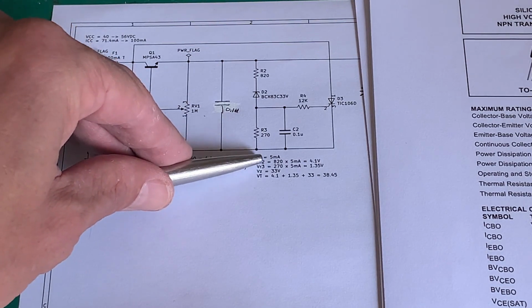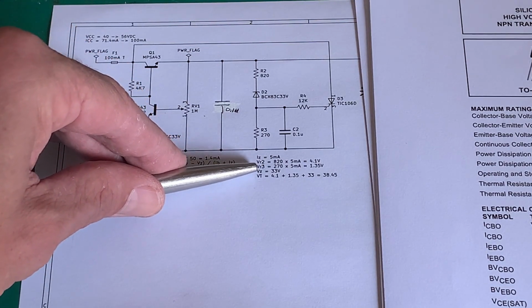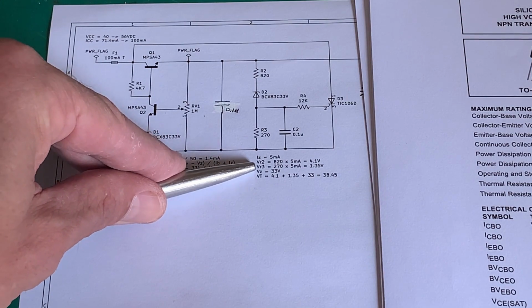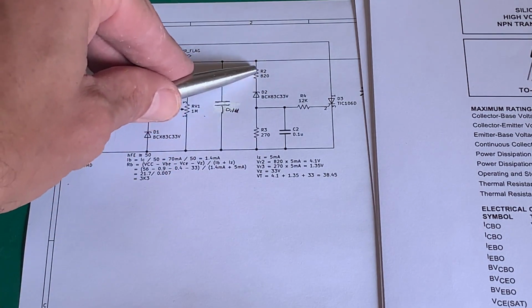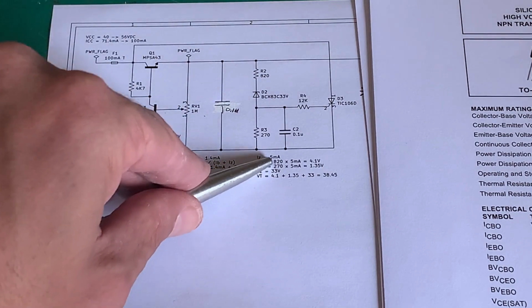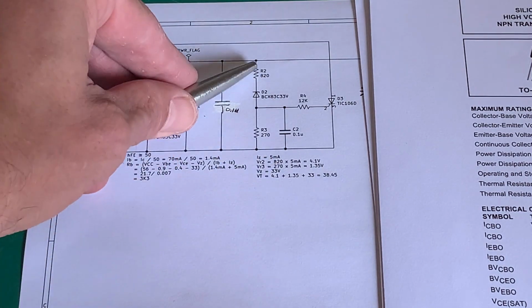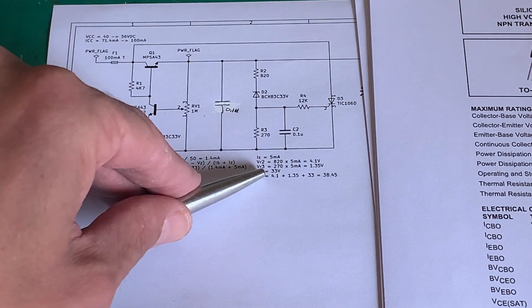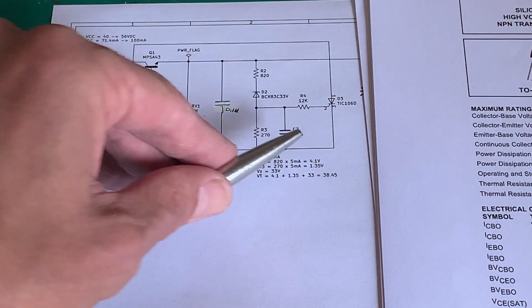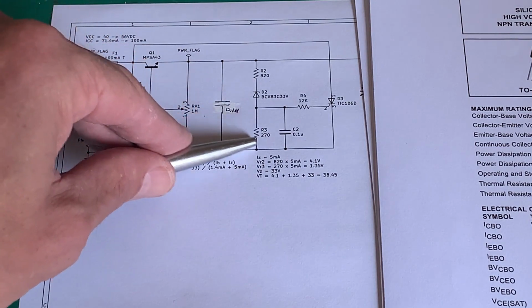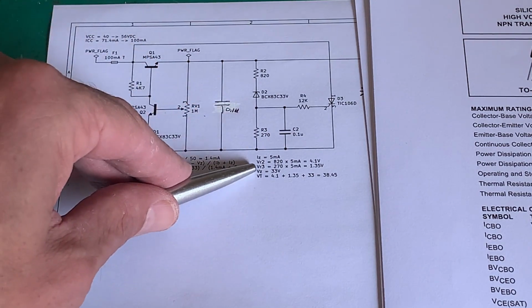We can see the IZ is 5 milliamps, and if we look at the resistance or the volt drop across that resistor, we take it as 820 ohm, which is what that is. 5 milliamps times 820 will give me 4 volts. And we've added another resistor down here, 270 ohm.